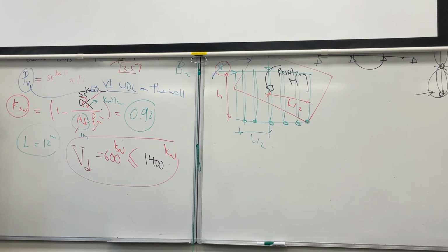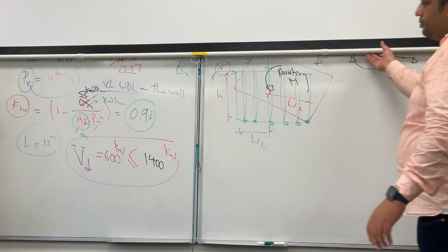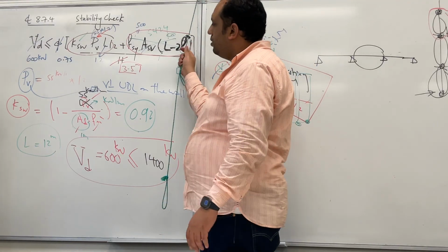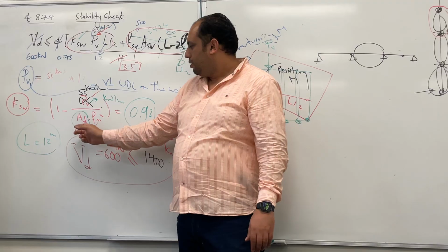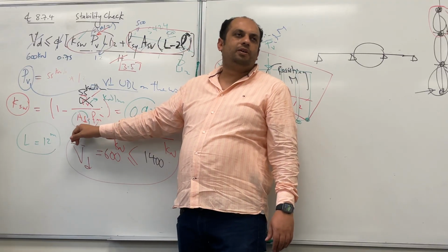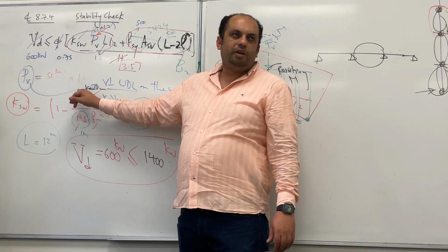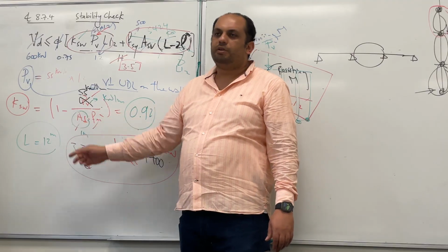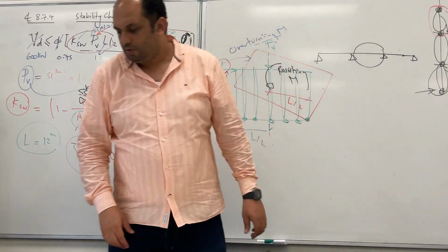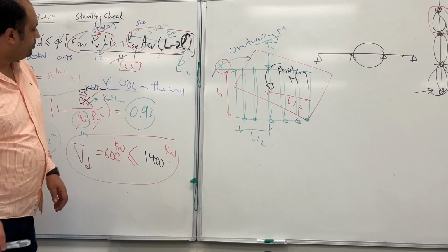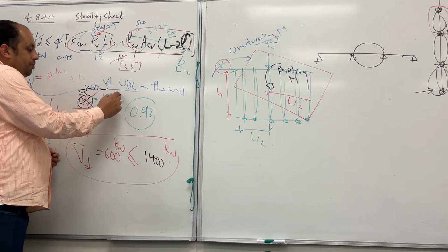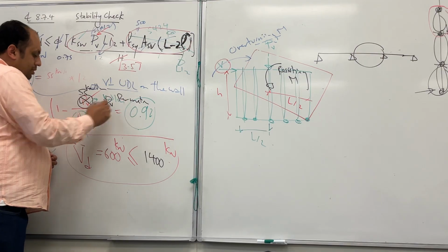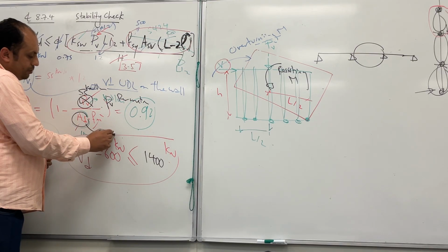Okay guys, again, for the times by 1,000, we have two locations for PV in the calculation here. PV here, because we calculate EV as per meter, so it should be per meter. Only if you take EV as per meter. If you take it as the whole wall, do it as a point load. You know the wall is 12 meters. So PV here is per meter, because EV here is per meter.